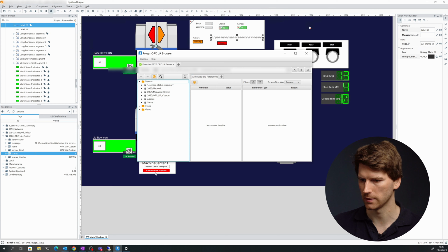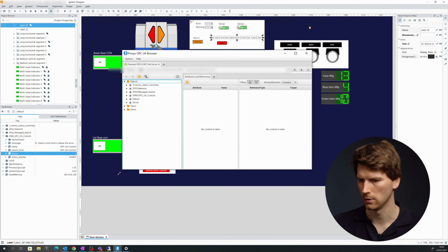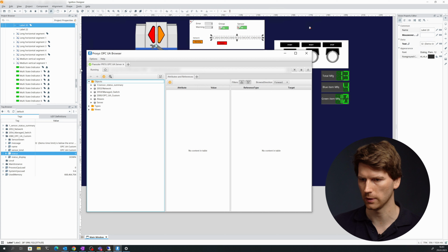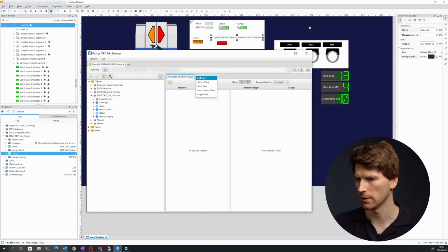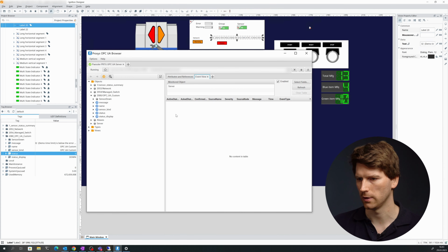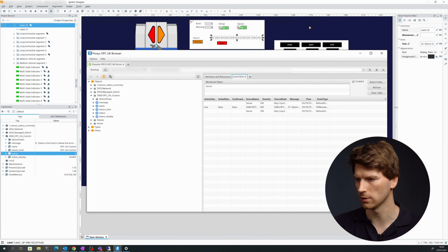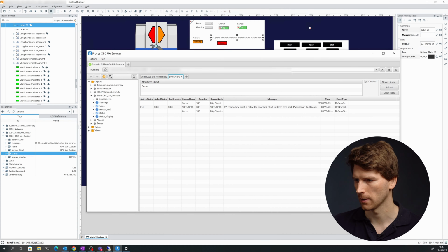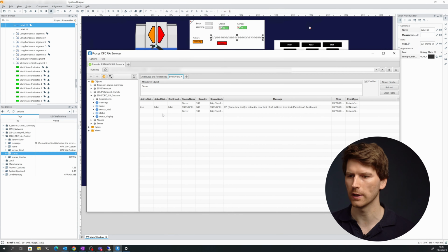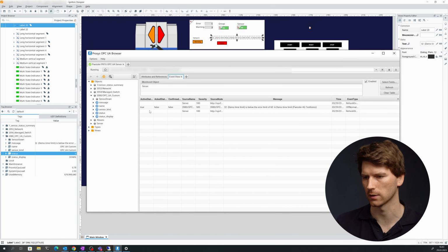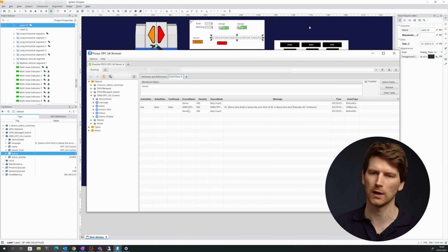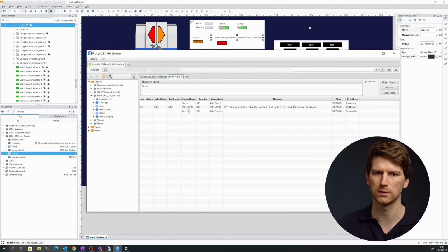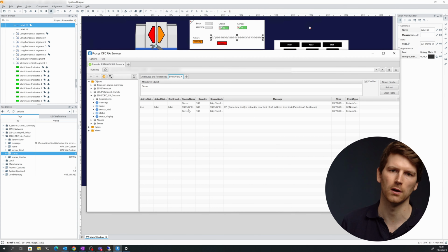And now we get basically the same view as we have here in the SCADA screen. So we see the sensor summary, the state of our network group, the switch, and the sensor. So what is different now, I can go here into the event view and actually get an event representation of our system. So I make it a little broader. And as we can see here, there's already one alarm raised inside the system, and the state is active true. And this alarm list view can be basically replicated in all control systems, DCS, SCADA, that supports alarms and conditions.